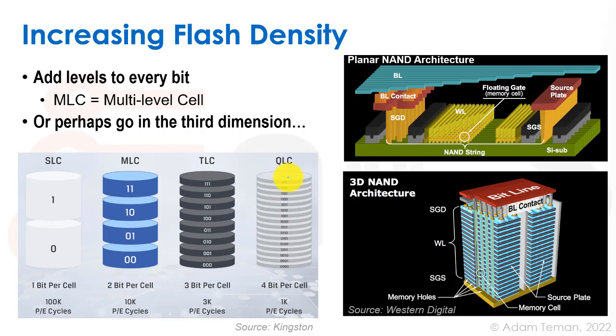And therefore there is a lot of information theory that goes into how we can really distribute the writes over the different areas of the SSD or the flash arrays, number one, and number two, of how we can really get rid of the bad cells and fix errors. So we don't actually get the number of bits that we fabricated, but this extreme increase in density still gives us a huge density. We have SSDs of terabyte and more than that nowadays, in what used to be, when flash first came out, a number of kilobytes.